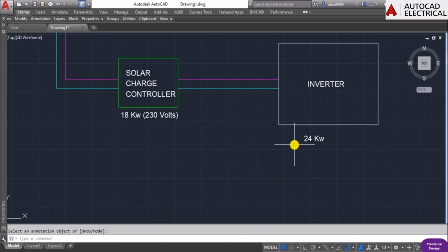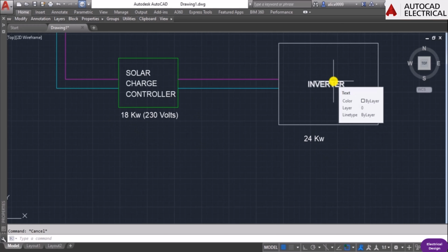That's why, when selecting for motors, we require triple the capacity of the normal type. So this is how to design the inverter sizing. For example, if my entire load is around 18 kilowatts, my inverter will be 30% more, that is 24 kilowatts. Now the inverter requires the battery.